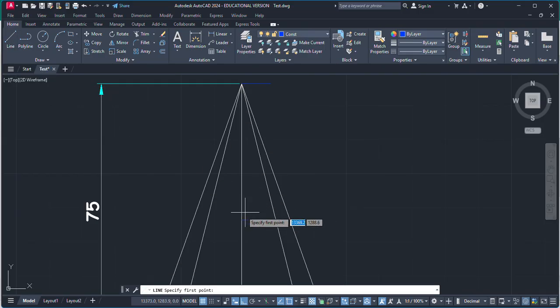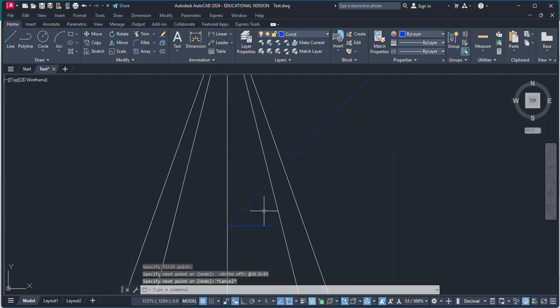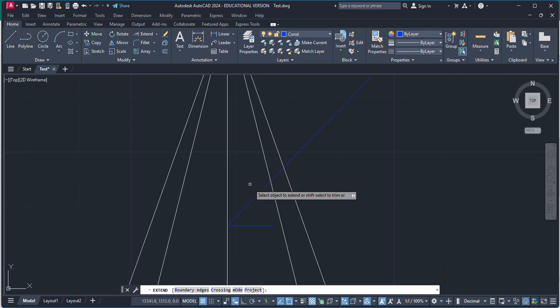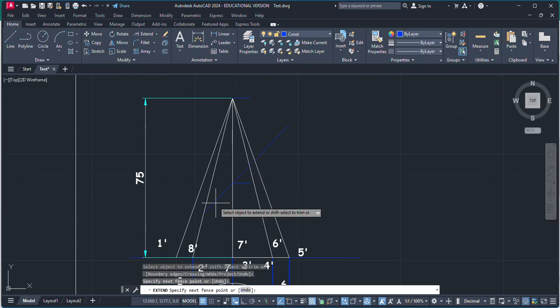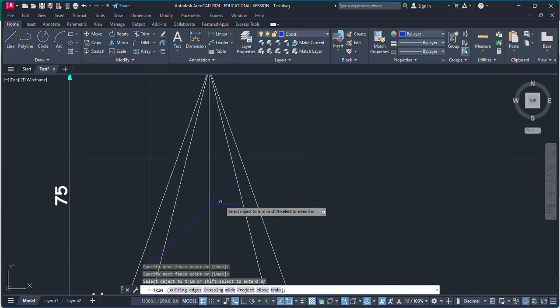So the plane is passing through this, and it should be at an angle of 45 degrees. If the plane is at an angle of 45 degrees to the axis, it means to the HP it is also 45 degrees. So just make it 45 degrees. Now if this is 45, then again this one will be 45, because the total is 90. So just mark this one, extend this from here to here. Now just going to remove this one.